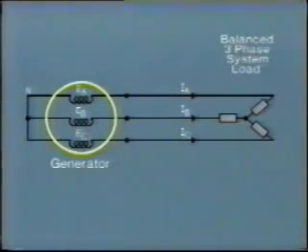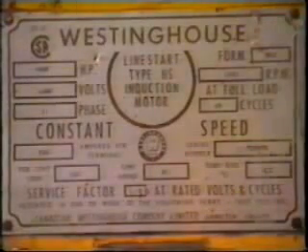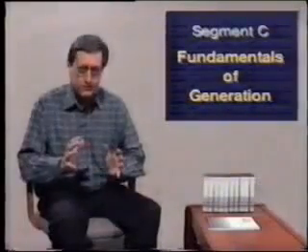We now have the conventional 3-phase system as you know it. The 3 outgoing terminals from the generator are connected by 3 lines to the 3-phase load, that is, the bus or power transformer. This in turn feeds the 3-phase power system. Most of the heavy loads on the system are actually 3-phase balanced loads, for example, electric motors. Moreover, single-phase loads, such as residential loads, are connected to the distribution system in such a way as to provide an approximate balance.